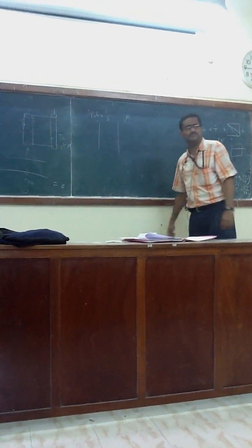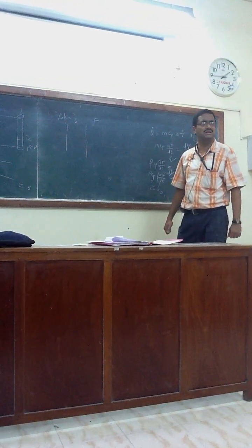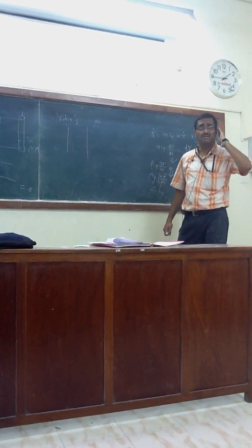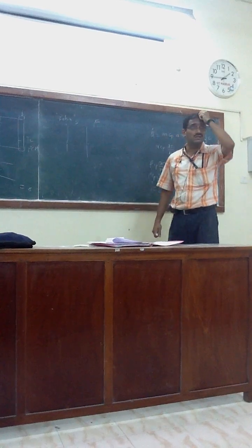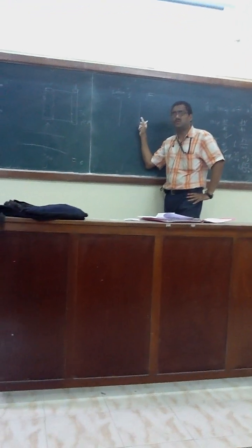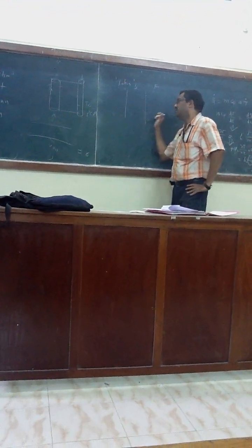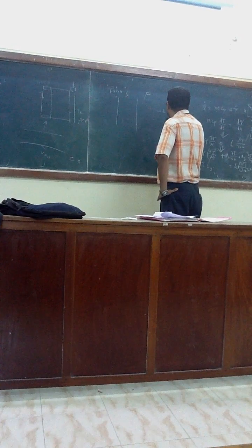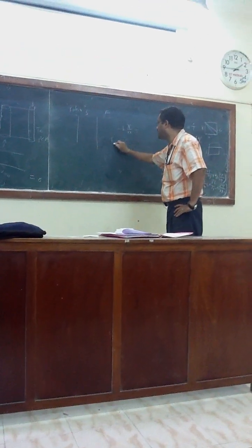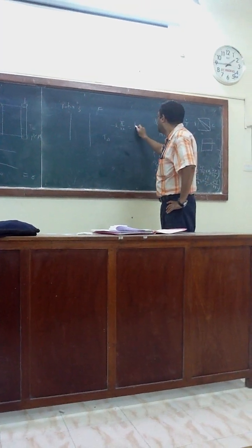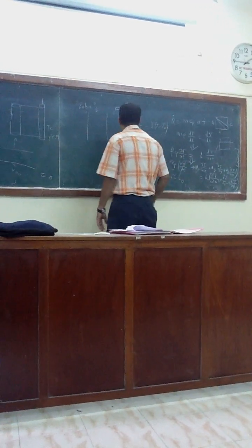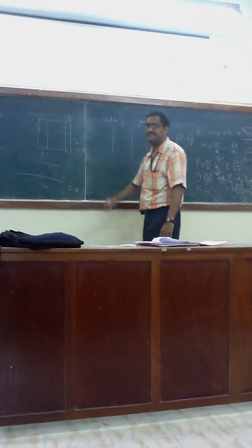What's the heat flux by conduction? You know the heat flux part. Minus K dT by dS equals, what's the heat loss by convection? How to write it? If the fluid temperature is T infinity, balance. This is called Robin's condition.